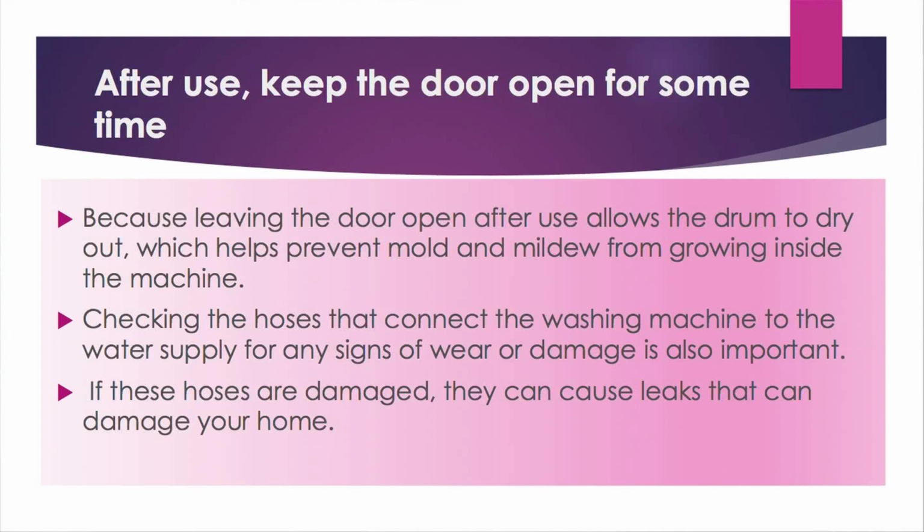Next point to be remembered, after use, keep the door open for some time, because leaving the door open after use allows the drum to dry out, which helps prevent mold and mildew from growing inside the machine. Checking the hoses that connect the washing machine to the water supply for any sign of wear or damage is also important. If these hoses are damaged, they can cause leaks and that can damage your home also.